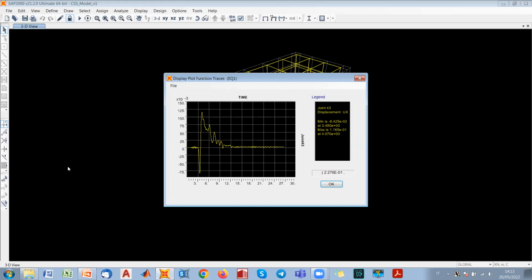Then there are also other issues, as we mentioned, that is the actual influence of the applied vertical load fluctuations during motion on the lateral response, and this is generally not modeled when we consider the analytical model of a single degree of freedom oscillator. So this is surely something that will be neglected for simplified models like the one we considered yesterday.